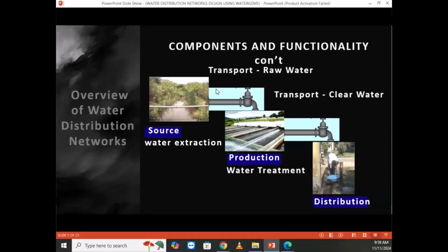So you will see it immediately in your model. Or if we drink water from here and bring water to this village, water will not reach here. But if we increase that portion of 1 kilometer, because you will see sizing, finding the solution of your network, and adding 1 kilometer, we increase this pipe to, for example, 150 to 200.